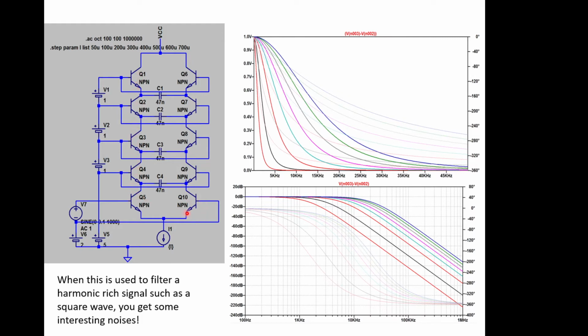One is the amplifier, and then these are the frequency control elements. What's happened is we've just connected a capacitor across the outputs of these 2 transistors, which gives us a sort of phase difference in the outputs between these 2. So we're building a sort of an RC time constant in.